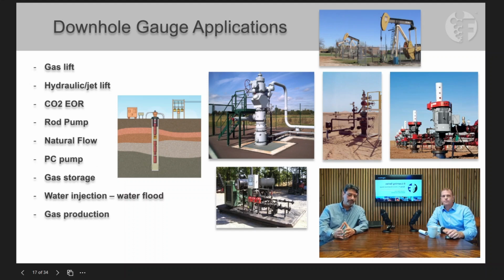For PCP pumps, operators basically try to understand the performance of the pump and diagnose any potential issues with the pump earlier. So what they do is they monitor the pump intake pressure, that's critical for a PC pump, the discharge pressure too. They want to know the differential pressure through the pump, and also vibration.